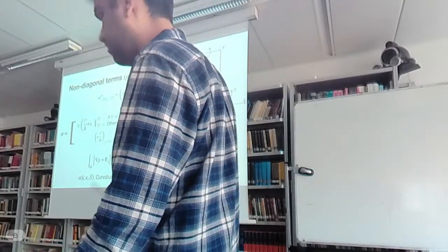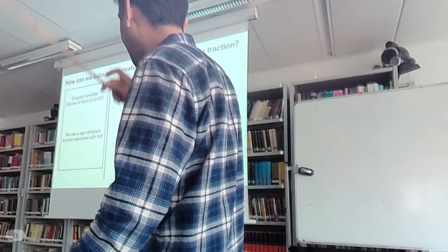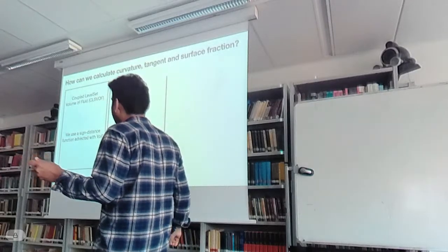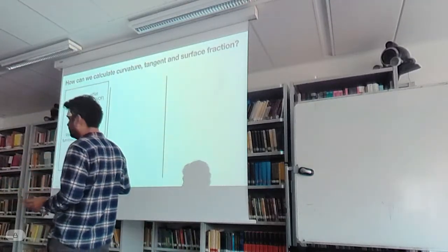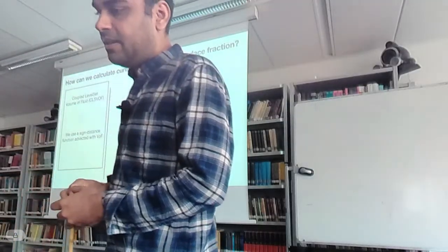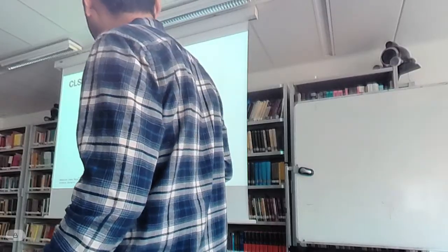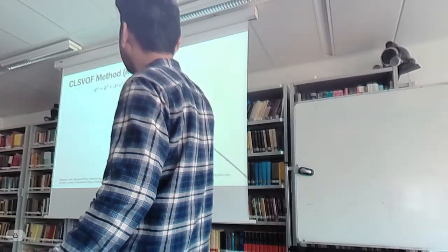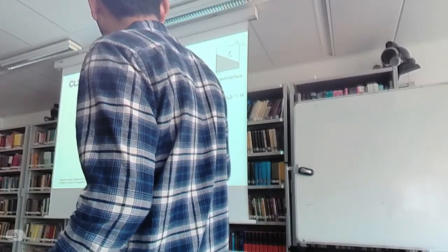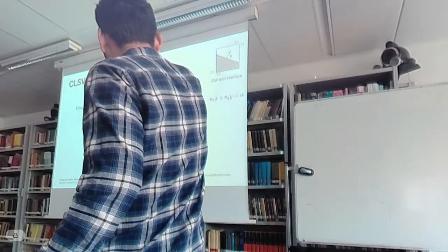And how do you do this from volume of fluid? So we had developed 3 approaches to do this. One is a coupled level set volume of fluid method. So we say we couple the signed distance function with the volume of fluid, and we do it as follows. So we have a signed distance function that is advected along with the VOF, and then this is coupled to VOF by weighting equation, which is this.